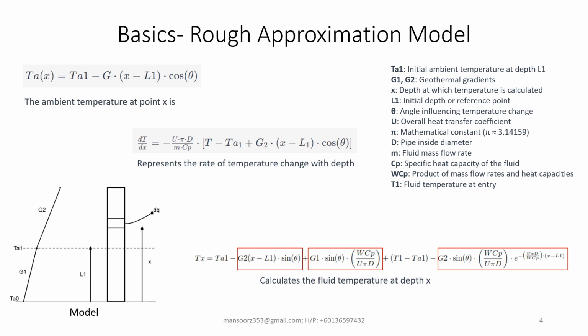It accounts for heat transfer due to advection, which is essentially convection involving the bulk movement of fluid within the wellbore. It considers the effect of fluid velocity on heat transfer, with higher U values leading to more efficient advection. So this formula combines both conduction and convection, making it suitable for analyzing temperature changes in a wellbore where heat transfer occurs through a combination of these mechanisms.